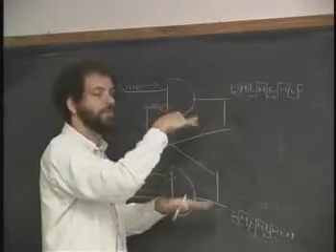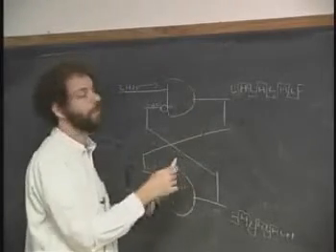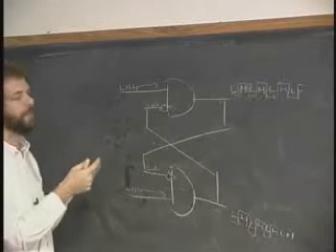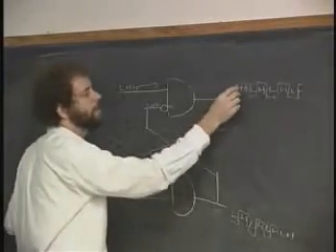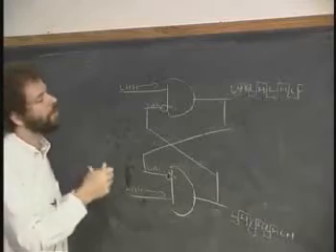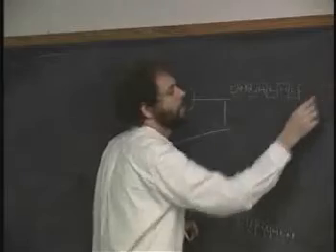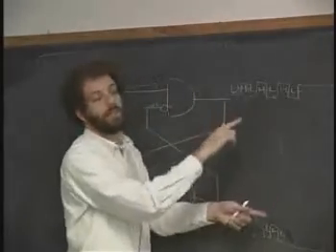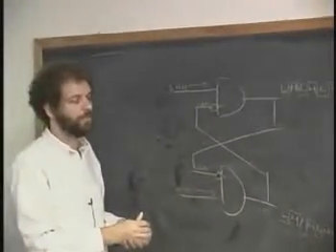It'll ring and ring and ring, flip-flopping back and forth, but eventually either the highs will grow or the lows will grow. You may think that it's impossible, since it's always impossible for two real values in the real world to have exactly the same value. The propagation times of the rising edge and the falling edge cannot always be exactly the same. And so it will always tend to extinguish the oscillation, and it'll end up being a value that's high or a value that's low, like that. Or maybe the other way. So even in the dynamic case, the oscillation will die down.